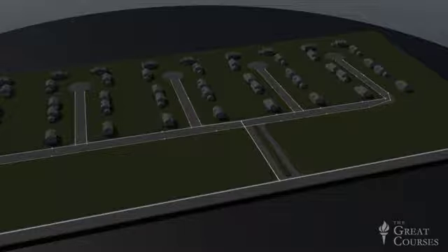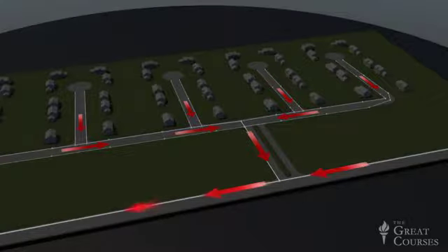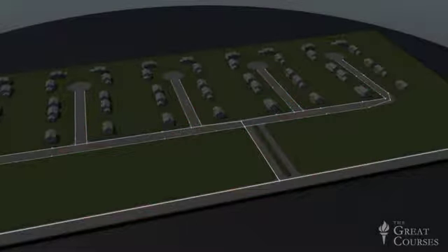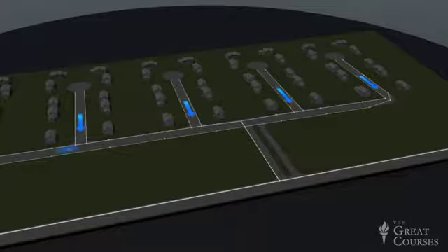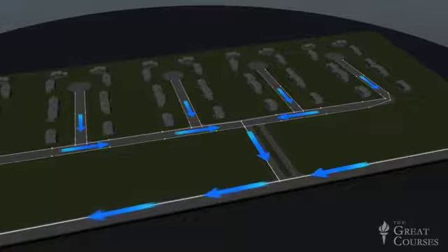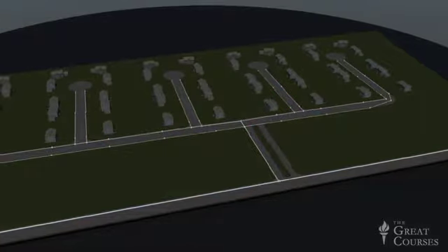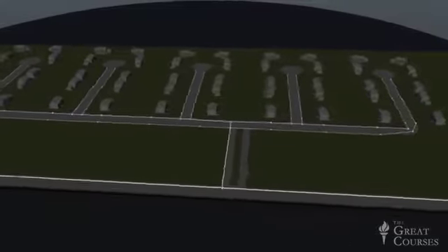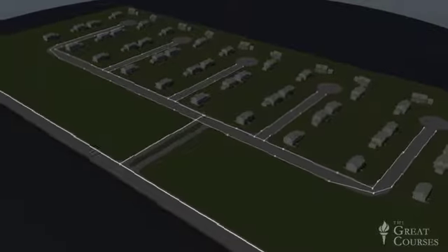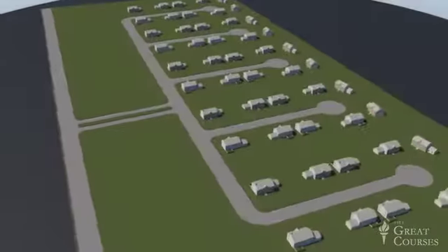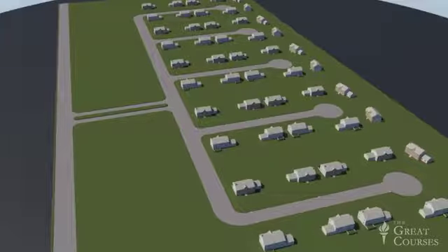All pipes in the system are placed on a steady downhill slope, so water will flow through the system by the force of gravity alone. The resulting network looks a lot like a natural river system, with a large river fed by many streams, each of which is fed by even smaller tributaries. And this similarity is hardly surprising, since the storm sewer serves essentially the same function of collecting and draining precipitation from a large area of land.